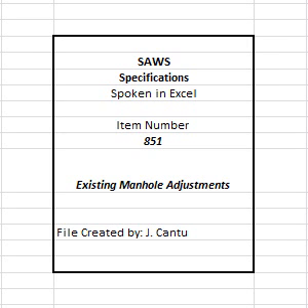851.6 Measurement. Manholes completely adjusted, as described above, will be measured by the unit of each manhole adjusted. The excavation and the amount of flowable fill, reinforced concrete, or any other material as necessary to fill the area excavated will not be measured for payment.